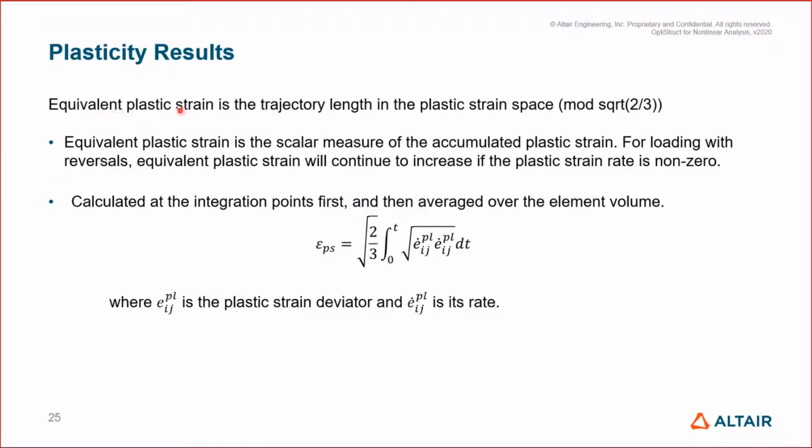We will also report this equivalent plastic strain. Just take note that equivalent plastic strain is calculated using this formulation here. Normally, especially Abaqus users, will use equivalent plastic strain. So that's why we have this result printed out, if they want to do a comparison or benchmarking with Abaqus results.